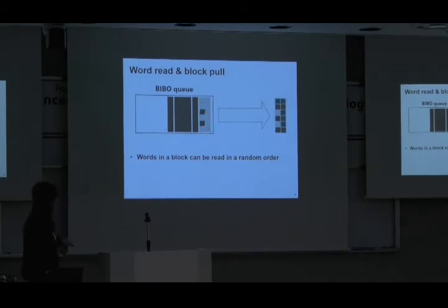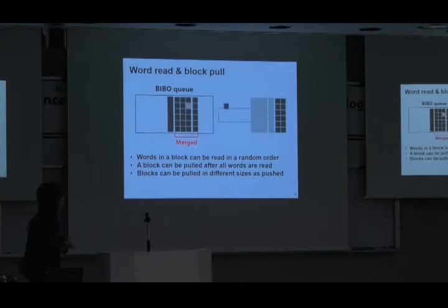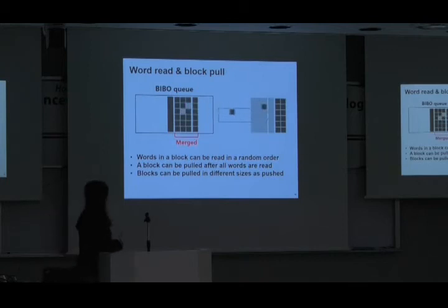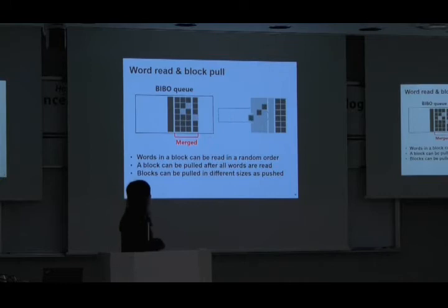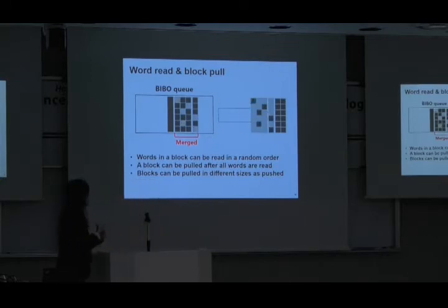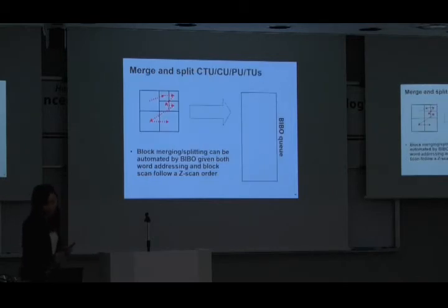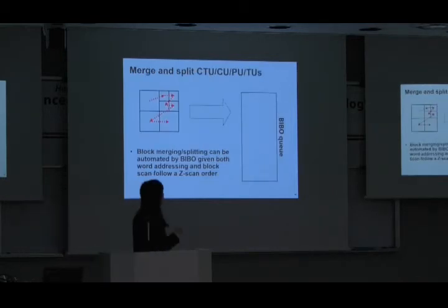You can read it in a random way, and then the block can be pulled after all words are read. Another good feature is that we can merge some blocks into one bigger one. It is also a good feature for some components. So, for example, when we use this BIBO, we can support any types of partitions of the CTU.